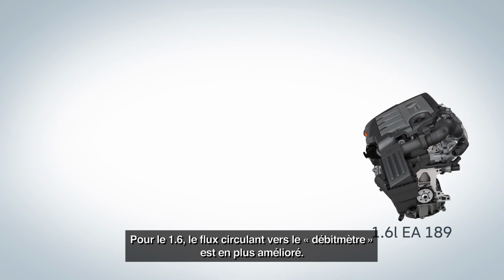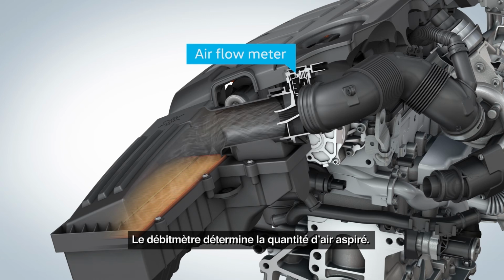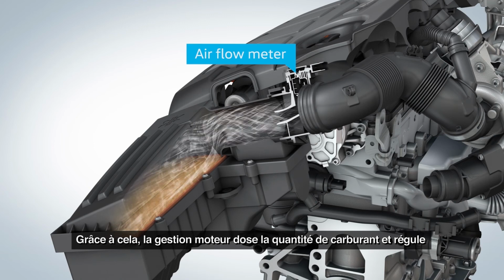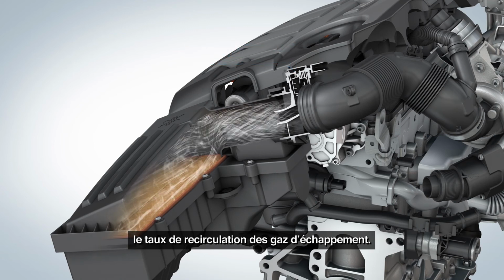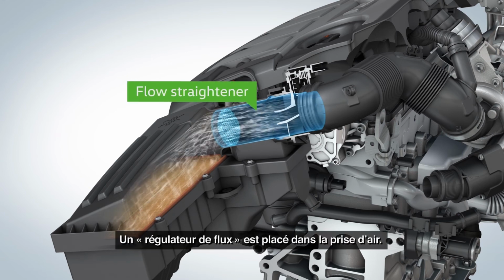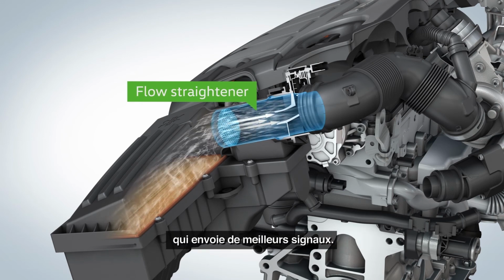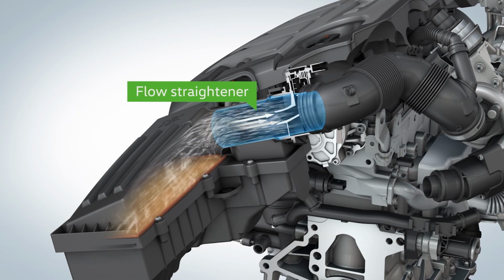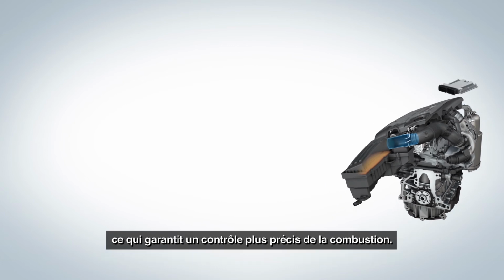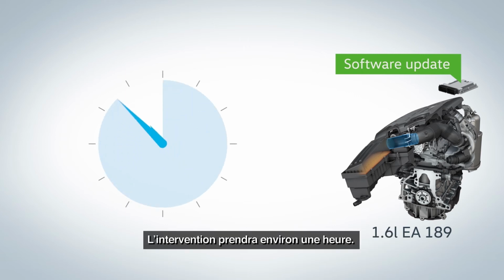For the 1.6-liter engines, the flow towards the airflow meter is additionally improved. The airflow meter determines the mass of the intake air. With this, the engine control doses the fuel quantity and regulates the exhaust gas recirculation rate. The flow straightener is set into the air intake. Its grid calms the flowing air in front of the sensor, which delivers improved signals as a result. With these improved signals, the engine control can more accurately measure the mass of the intake air, and this ensures a more accurate control of the combustion. This refitting will take approximately 1 hour.